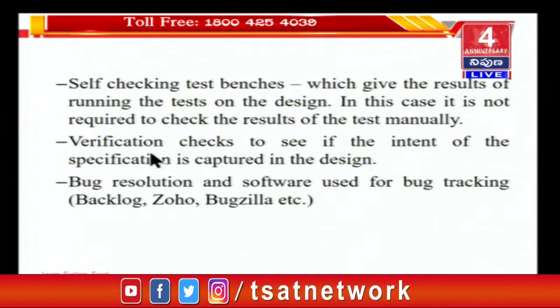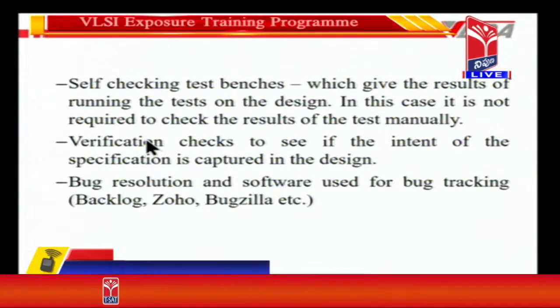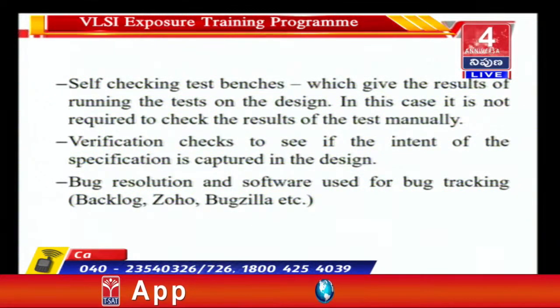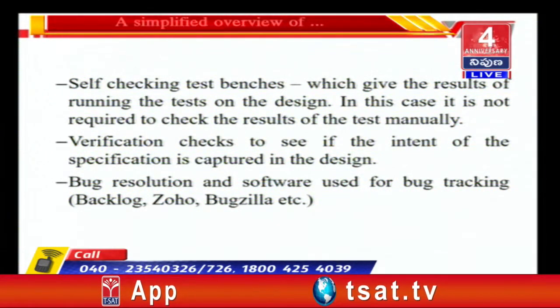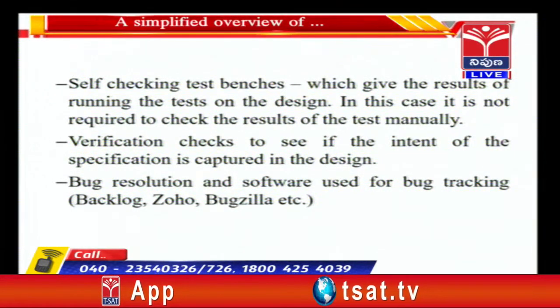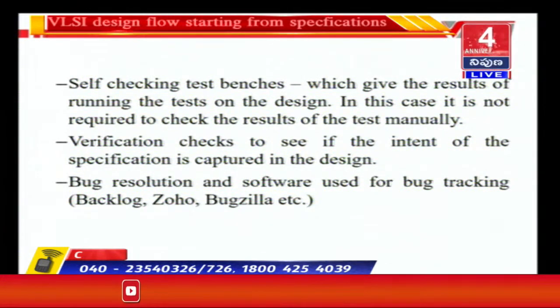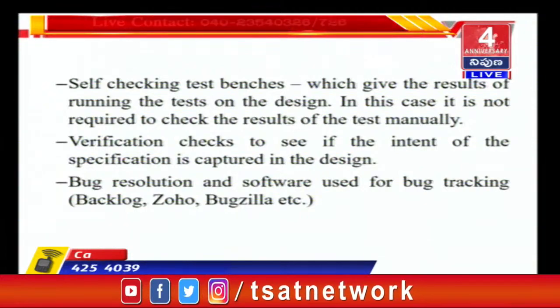What does verification do? Verification checks to see if the intent of the specification is captured in the design. That is what verification is. It is different from testing, because testing, if you go by the pure word of testing, means that you are trying to see whether a particular design has been manufactured correctly or not.